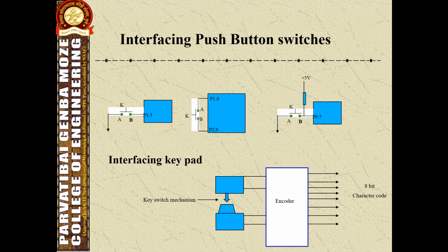In the case of push button keys, the metal contact bounces a few times, hence the voltage across the switch fluctuates and generates a spike in the signal. Therefore, it is necessary to debounce the mechanical switches. Key debouncing is done through hardware and also software.